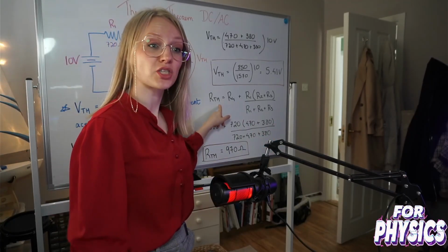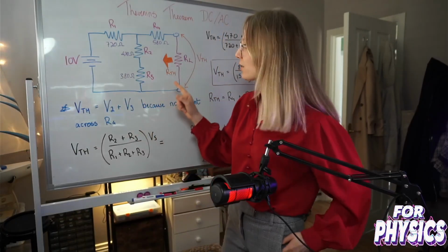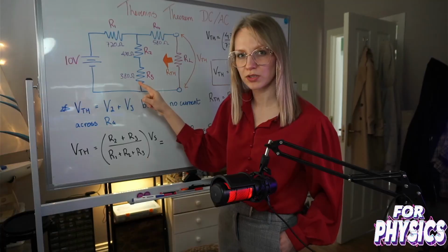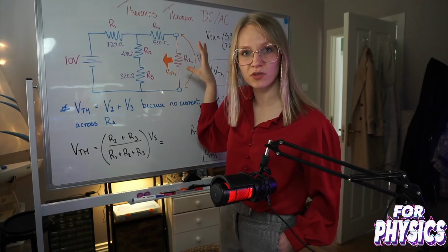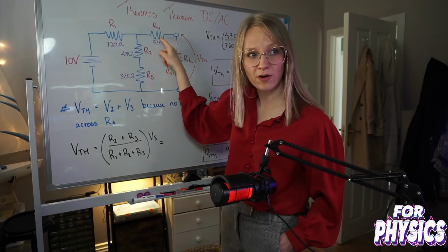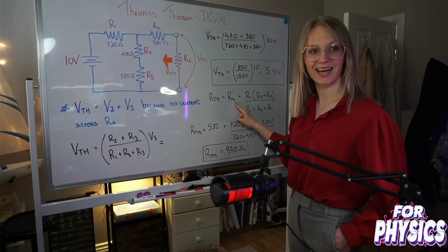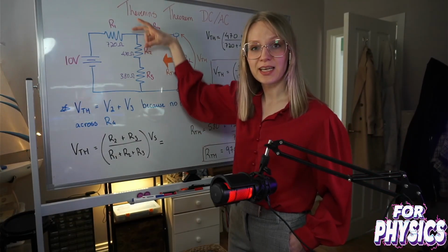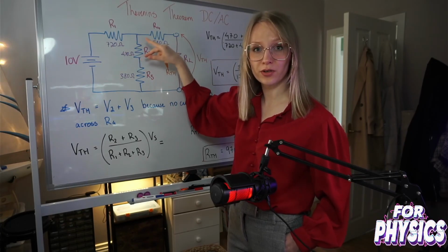The next step is to measure the resistance that this body will experience. So let's look at our diagram again. You're not measuring the resistance of the total circuit, but rather, what is the resistance from the perspective of the load? You start here and follow the path of the current. The first resistor you meet is R4. Ta-da! The next resistor you meet is 2 resistors in parallel, R1, and R2 and R3 in series.